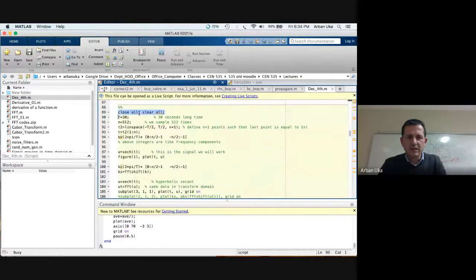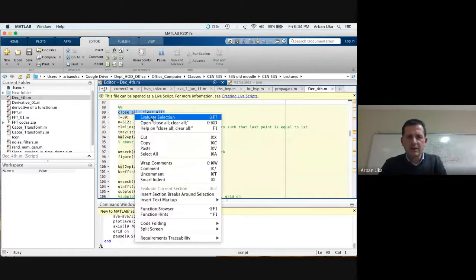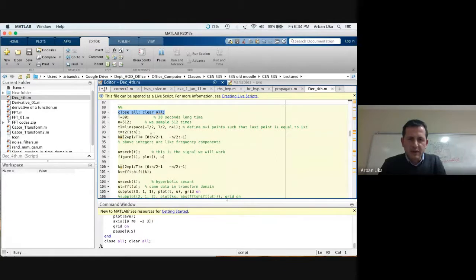Now let's see another example, and in this example, apparently, we can generate a signal which has 30 units of length in one axis. So this could be x, this could also be time. We are not assigning any value right now. But once we do this domain, or this complete range of 30 units, let's call it time, we also assign 512 data points over which we're going to discretize the time axis.